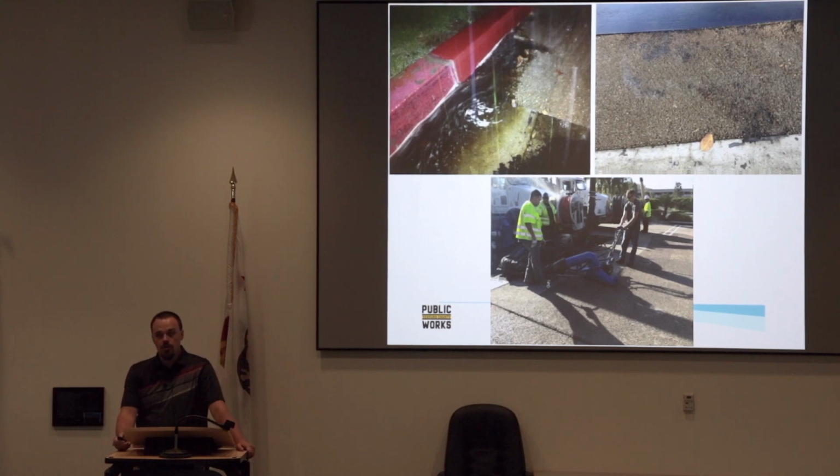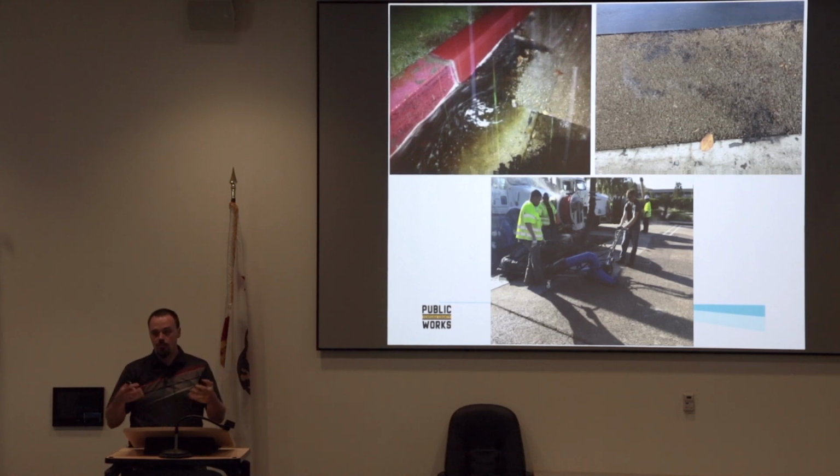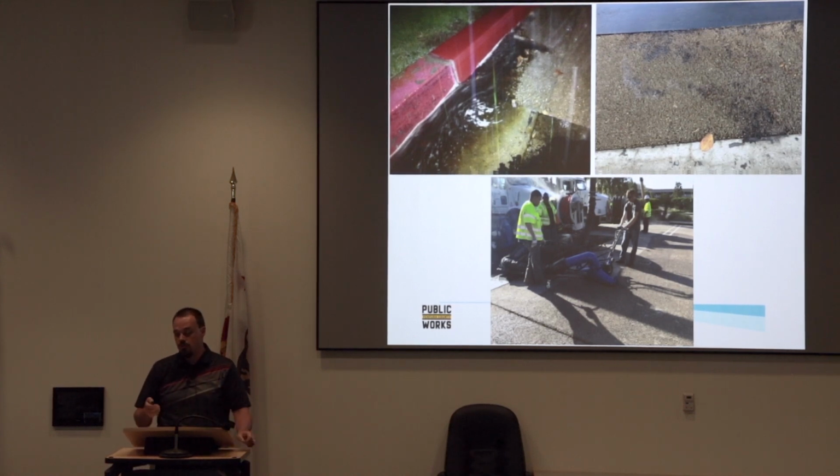This is something that's fairly new. It's a company called Bunyan Industries creates a system. It's called the Bird system. And it's got 12 pressure washing jets in the head, as well as suction and a rubber gasket around it that's adjustable, so you can always make sure you have good suction on the ground. And then you just pull it along like a household vacuum kind of thing, and it just sucks everything up while it's pressure washing and loosening up those sediments.